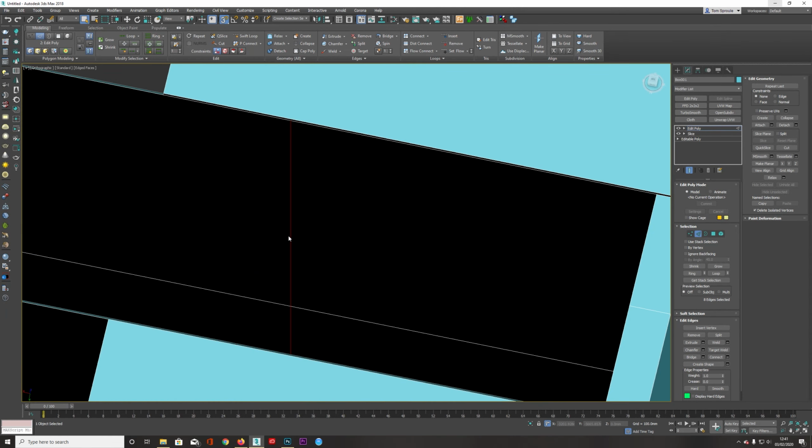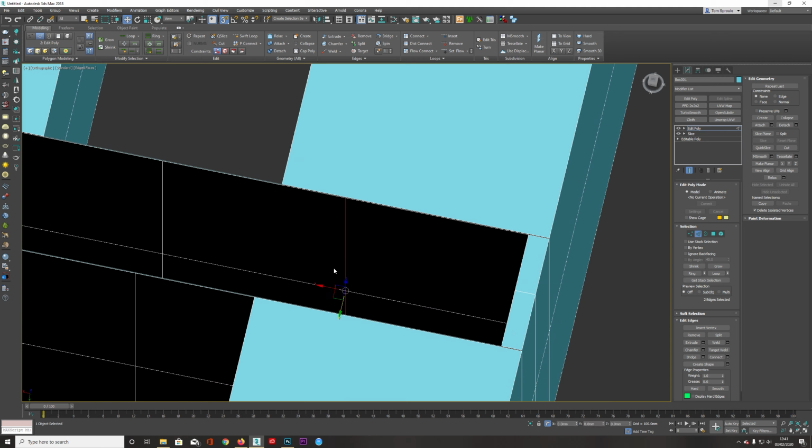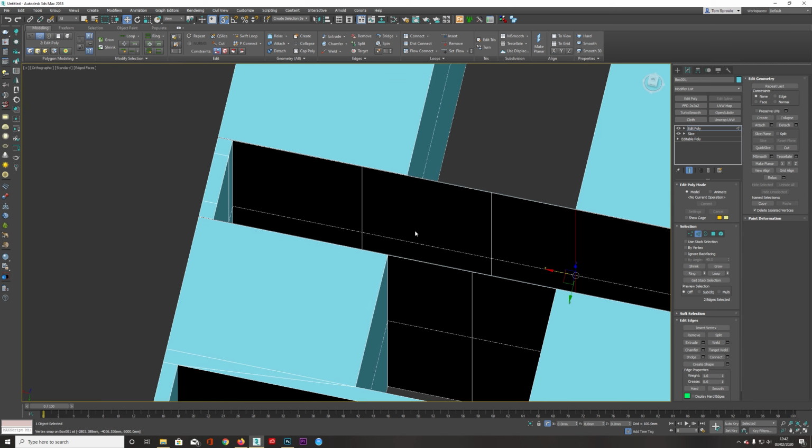And then what I want to do is line this up. I'm going to press W again, and I'm going to turn on the snaps. So I need to move this now, I turned off snaps. Turn on snaps, just look at that, make sure it's on. And like I said here, by having enable axis constraints on, it stops it, when I move it, from going on all different angles, and I can just move it on X and then snap to that one there.